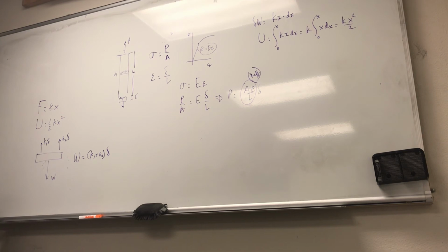But on this side, you have the suspension system of the freight truck with a parallel spring arrangement. Find the equivalent spring constant of the suspension if each of these helical springs, of course, you remember this from your machine design. This is not just a regular kind of spring. The spring stiffness for this type is a function of the diameter of each one, the number of turns, obviously, and the modulus of rigidity, or the shear modulus, essentially G. So you compute one for each one, right?